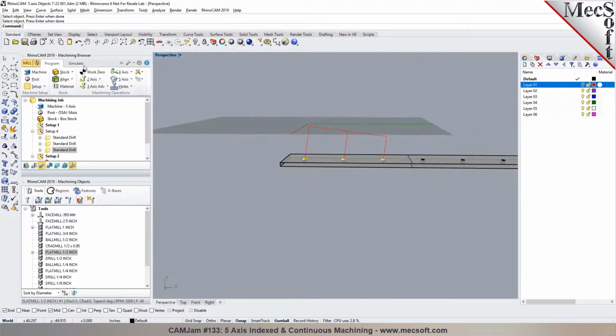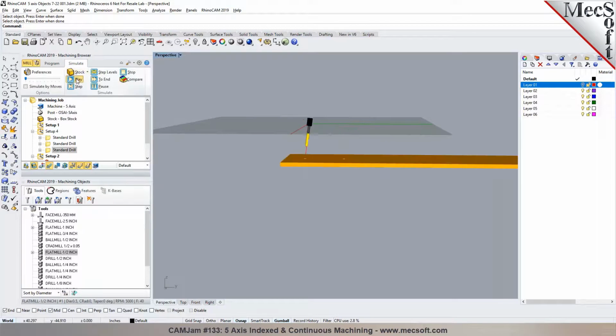Do you notice that, sir? I do. Yes. Because the clearance plane is parallel to the tilted plane or the setup that you have. So in this case, the retract motions are going to go much higher. So to make it efficient, we can just break it up into multiple operations. Okay. I understand. Yeah. So rather than having to retract all the way up to this point.